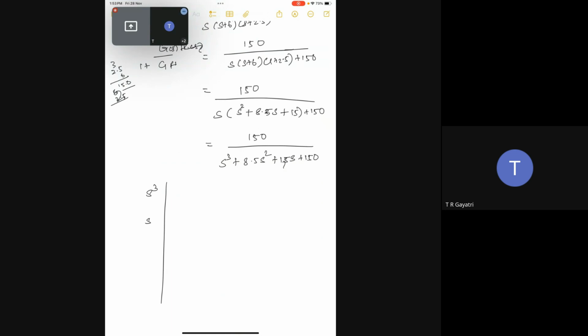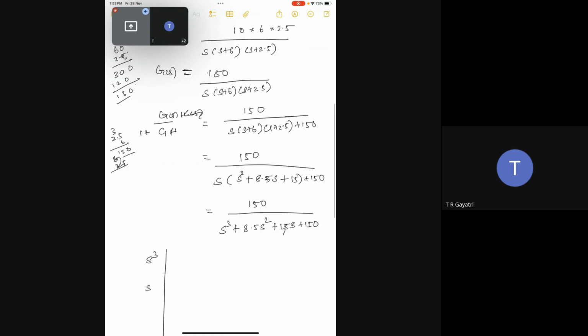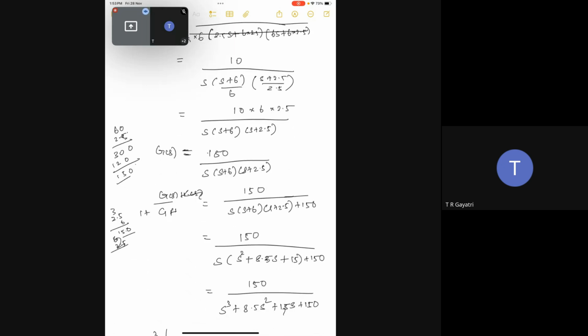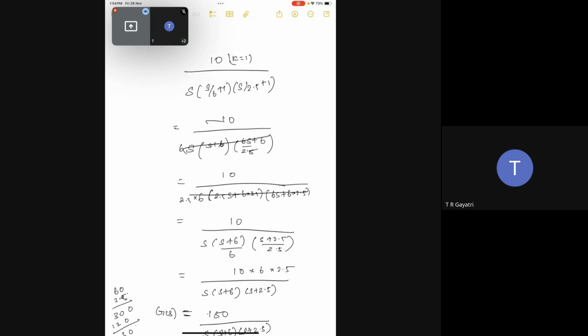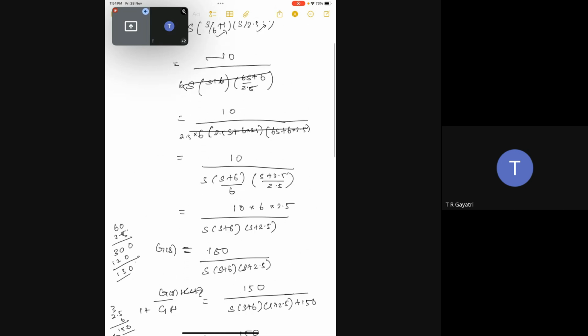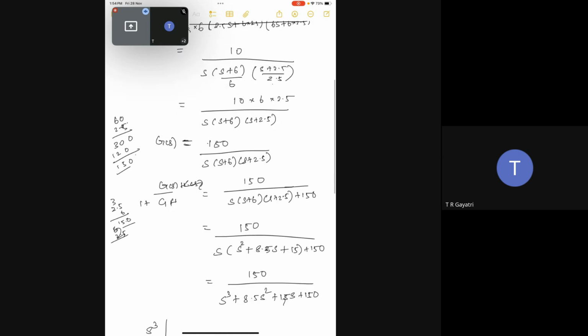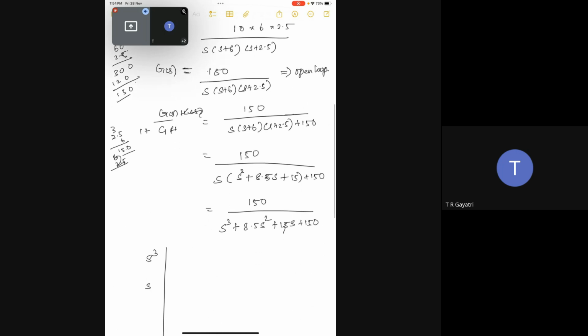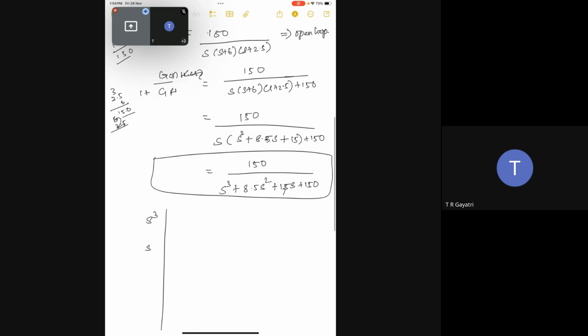Yes, ma'am. Okay, right. Now, what I did is I just calculated this, multiplied this 6 here, 2.5 here. This I'm telling for people who are listening to offline videos. So I have multiplied the 6 here, 2.5 here, and took the 6 and 2.5 above here. So the overall open loop transfer function will look like this. If I calculate the closed loop transfer function, this 150 will come here plus, since I'm assuming unity negative feedback. So this is your overall closed loop transfer function.